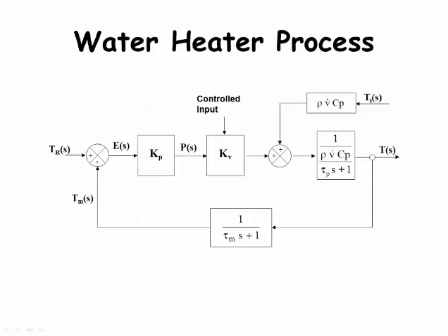We will use the water heater problem to illustrate the procedures and MATLAB commands needed to plot the time-dependent response to a step change for the servo problem when we have a set point change in TR and the regulator problem when the inlet temperature TI changes. We will use different control modes including proportional control only, proportional plus integral, and proportional plus integral plus derivative control. I will also change the feedback element response. Here is a block diagram with the respective element transfer functions.